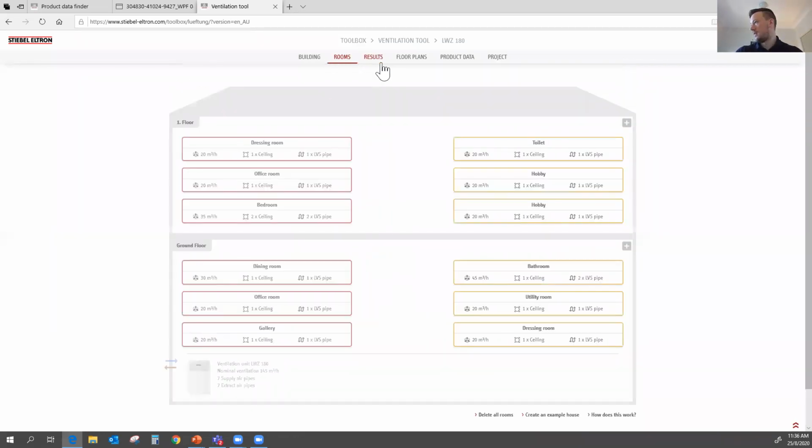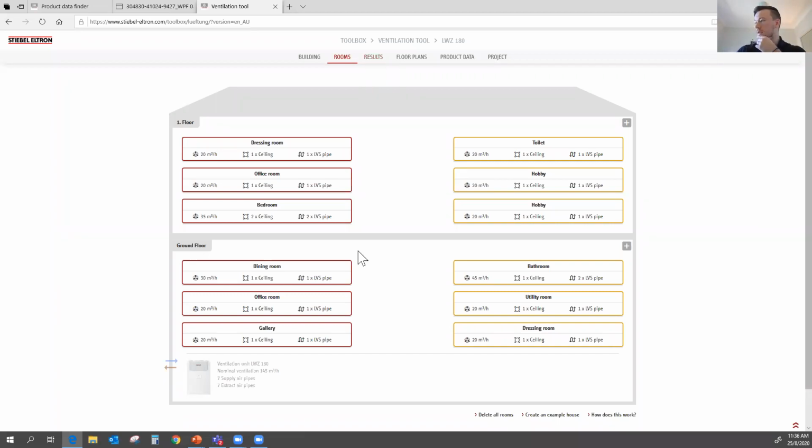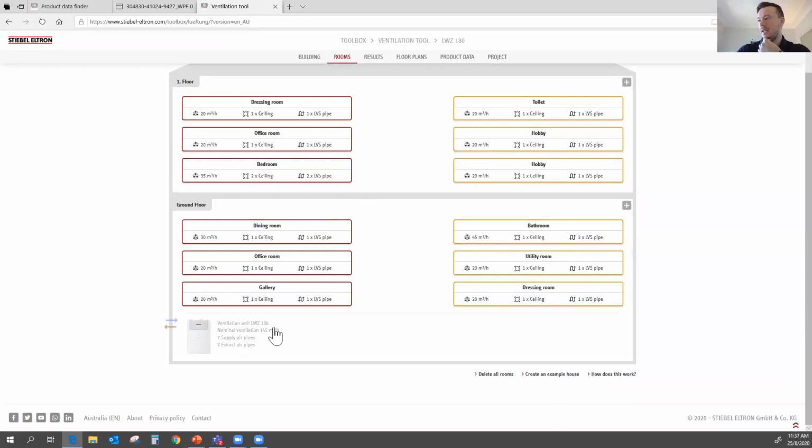I should have maybe said the nominal ventilation is what we would recommend to be constantly running in terms of nominal speed. So there's multiple stages. This is the stage at which, if there's people in the house, the system should be running. And this is in order to hit that target of 0.4 to 0.5 air changes hourly, meaning every 2 hours, we swap out the full content of the home's envelope in terms of air. So the volume is completely changed every 2 hours. All the stale air out, fresh air in. That's a good European standard that we use. And this number, the 145, ideally can achieve that.